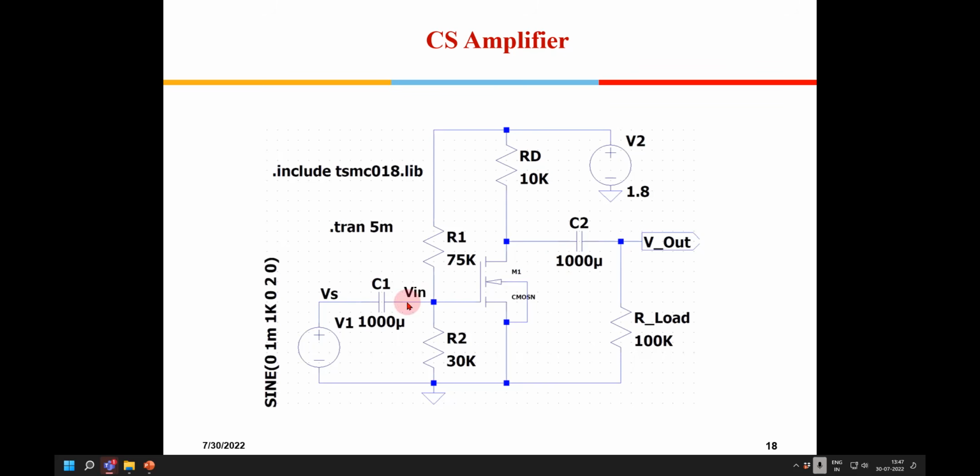So you will get at least 10 times the amplified output here, audio signal, right? So that will be known as the small signal. Whereas for this MOSFET, if I give just a few millivolts, this MOSFET will not be switched on at all. The voltage generated by the mic is plus 10 to minus 10 millivolt. If I put it here as a 0, this will be off only.